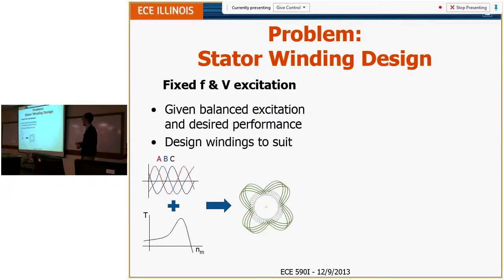In some conditions, let's say you're operating as a generator in a 7-phase system, you might want to minimize a certain harmonic, like the 13th and 15th harmonic. Or in a 5-phase system, you want to minimize the 5th, or you want to minimize the 9th and 11th. So those are tricks you can play based on your system.